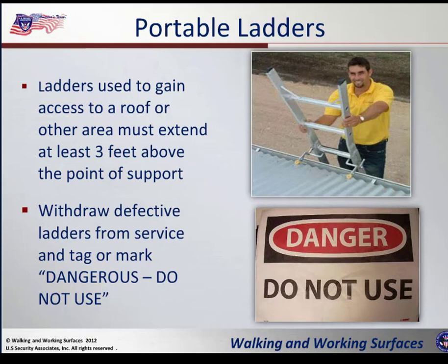Also, make sure you withdraw from use any ladders that are unsafe. If it's broken, maybe it's missing a handrail or a piece of step, don't use it, okay? Don't allow anybody else to use it. Mark it as defective, as dangerous. Do not use.